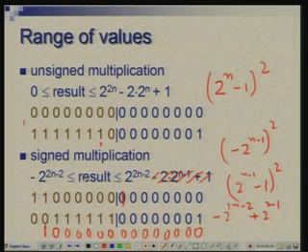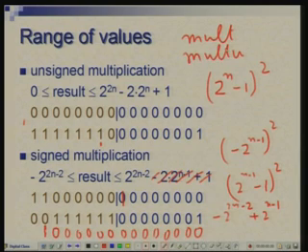So, MIPS has mult and multu, two instructions are there, mult and multu. I think in the last lecture I placed it wrongly in the group where overflow is detected and there is no difference in signed and unsigned operation, but actually there is a difference between these two. multu will interpret the two operands as unsigned integers, right.